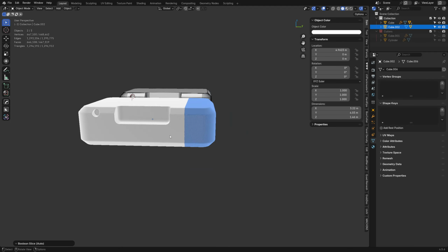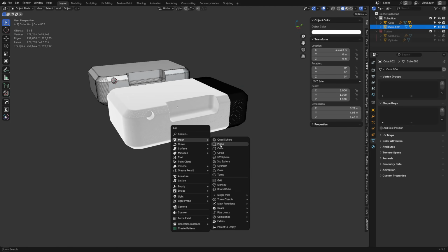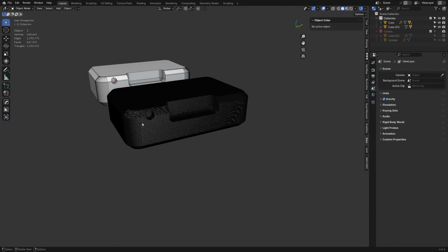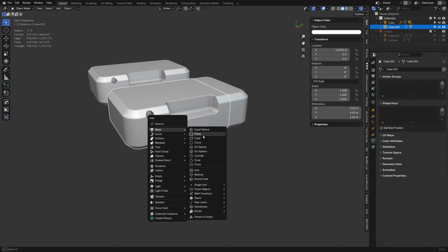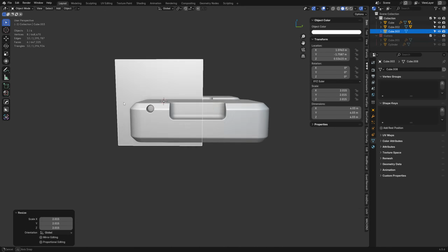Okay. Now, this is important to do it destructively without previews. So if you're trying to use Box Cutter, for example, turn live preview off so that it's destructive. It'll work better this way. As far as setting Hard Ops to work destructively, I'm not sure if there's a way, actually, to be honest. I haven't really tried. So yeah, I just use Bool Tools. It's easier, I guess, in that sense.